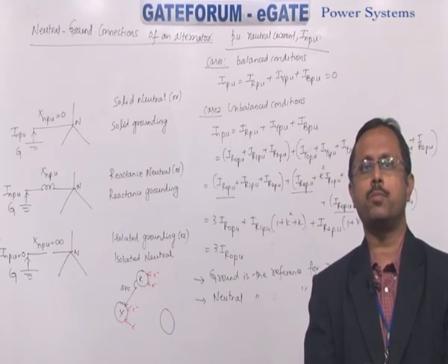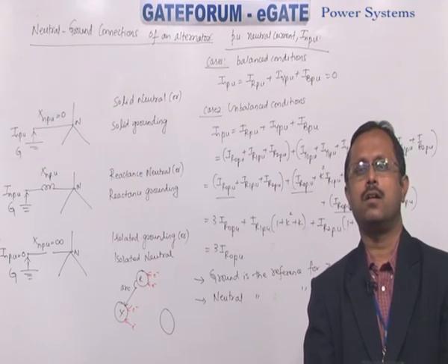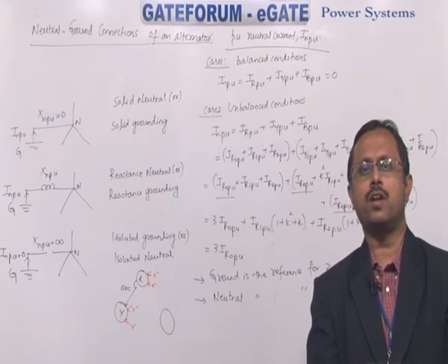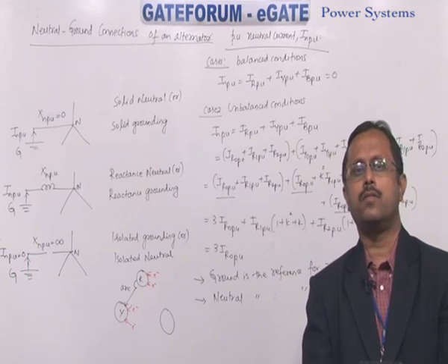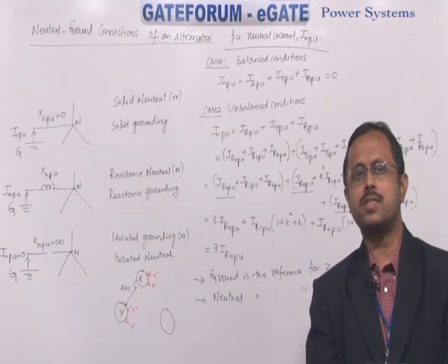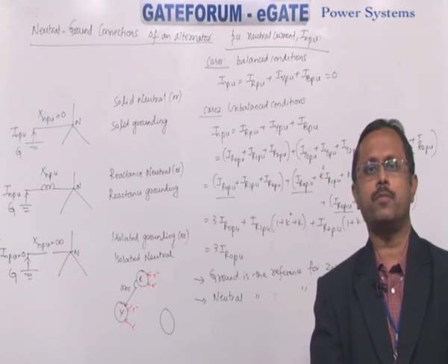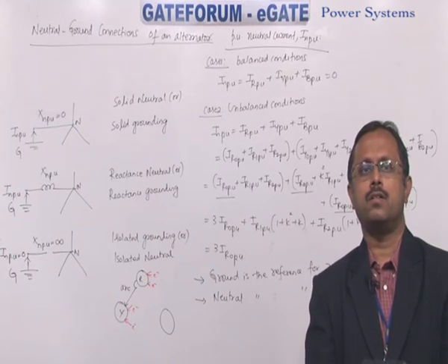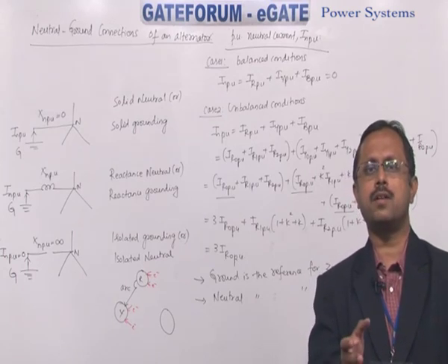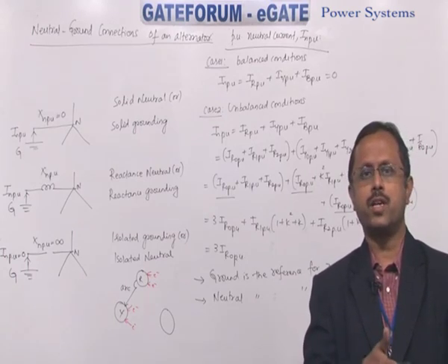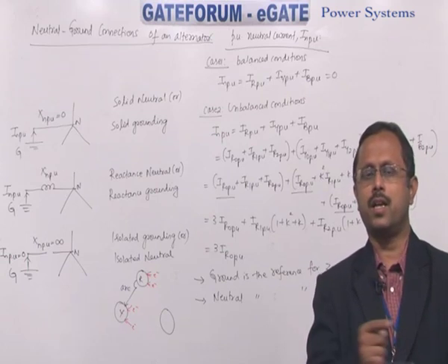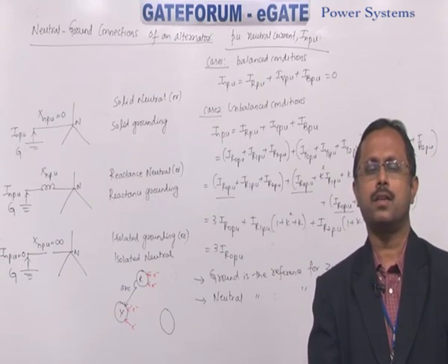Next question is by Somdev from West Bengal. What is the equation for load current for negative and zero sequence component to find value from the figure? No, load current depends on what? Eg minus Vt divided by the reactance of the path.